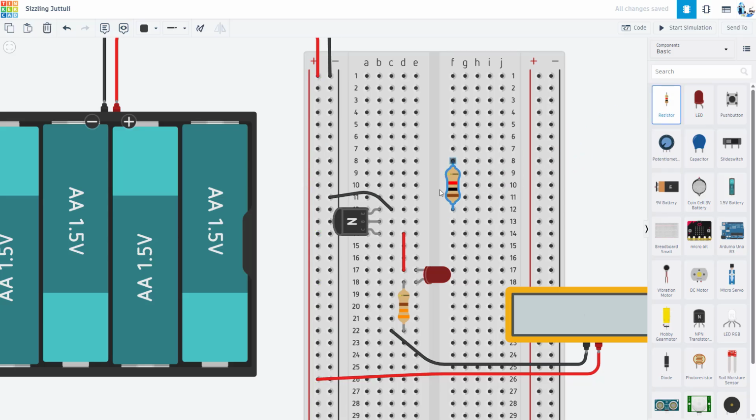You need a base resistor. And again, go back and check out the theory video if you'd like to see a little more behind this. I'm just going to go with the default value of 1 kilo ohm, connect that to power, and now we will see if I start the simulation, my LED turns on and I have some current flowing through the LED, which is coming from power through the LED, into the collector, and out the emitter, which is separate from the current that is flowing into the base.